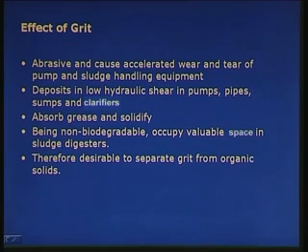Clarifiers are the sedimentation tanks which we are going to use. All this grit is going to settle down there whenever there is low hydraulic shear. Low hydraulic shear means when we do not have much velocity, and they absorb grease.